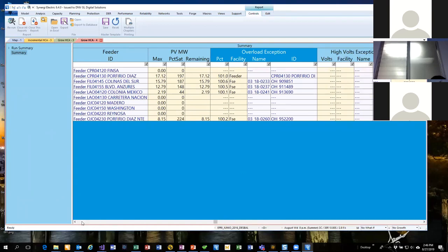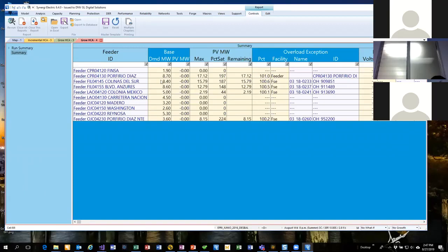But you can see how this application works. It gives you megawatts for each feeder. Then you can have a system that is adding up the connected PV, and if that total exceeds this, then, well, you've exceeded the hosting capacity.